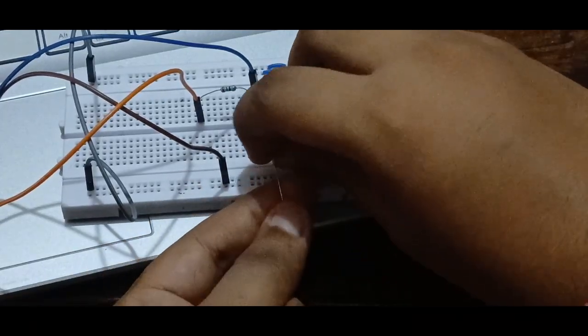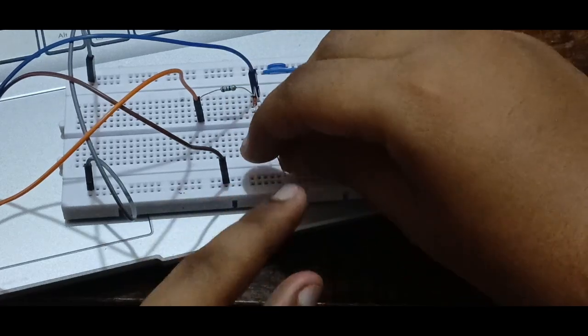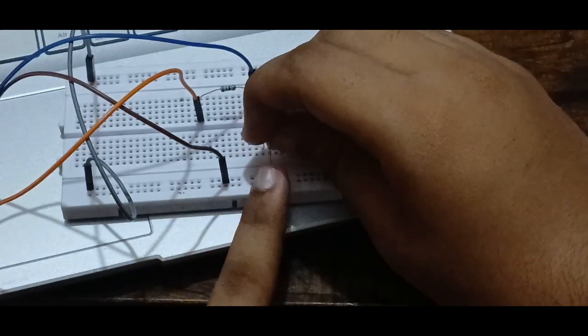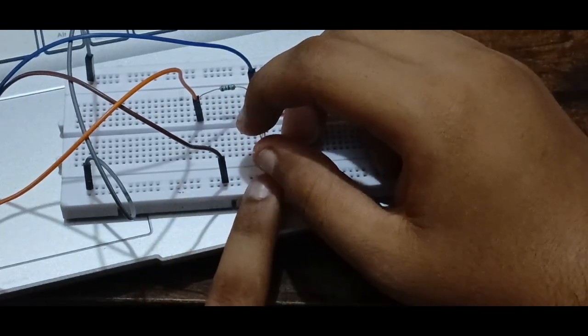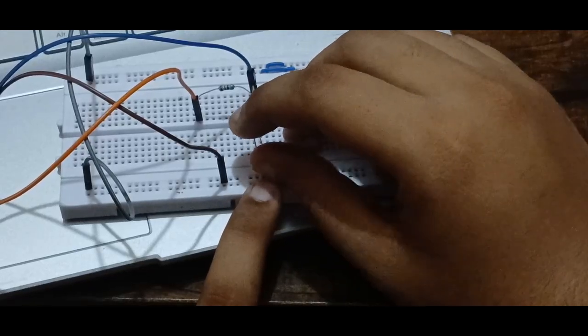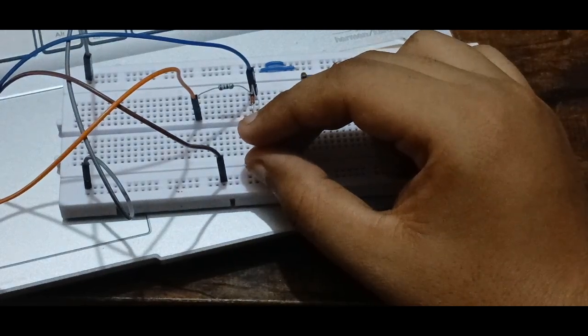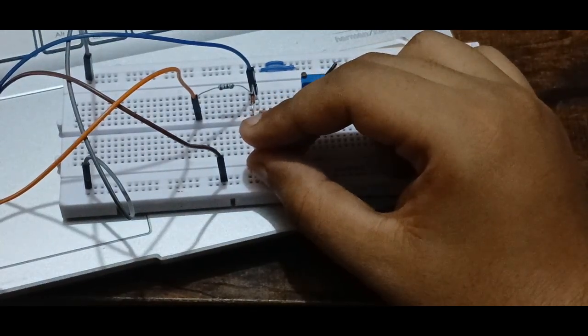The breakdown voltage is 3.6 volts for the first Zener and 3.6 for the second, so our total is 7.2. After 7.2, it acts, and the voltage is going to vary.